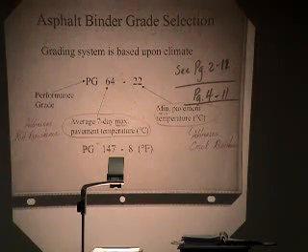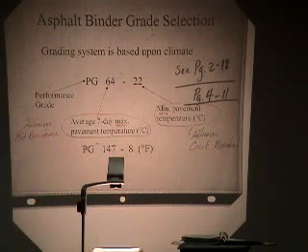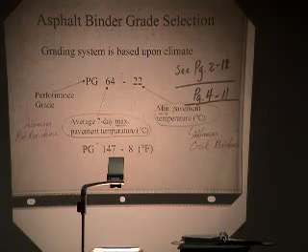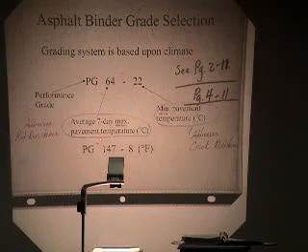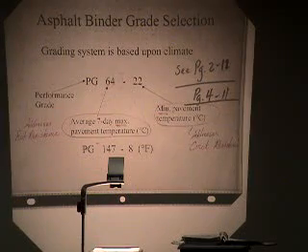And there are many grades, as Bob mentioned back on that chart on page 2-11 of the manual. Obviously, we wouldn't use all those. In fact, we don't need all of them. The way you select the grade is to go out and actually do surveys based on a given location to find out what the maximum and minimum average 7-day temperatures are and so on.